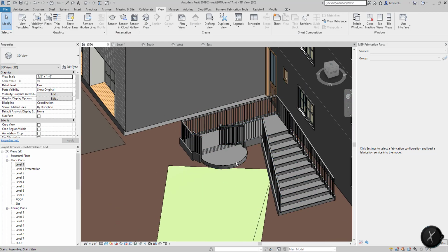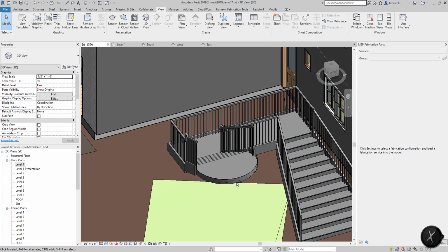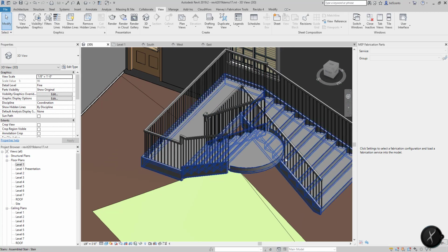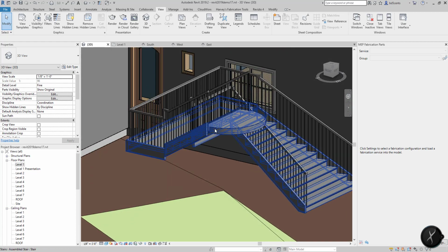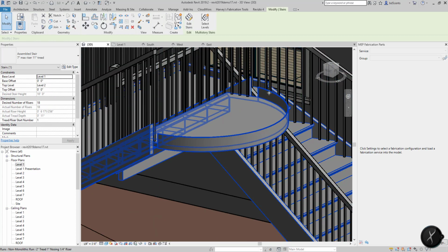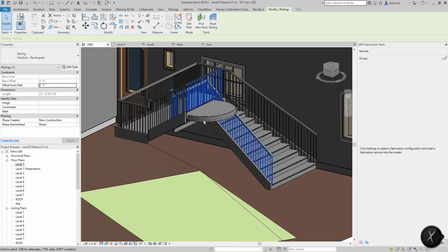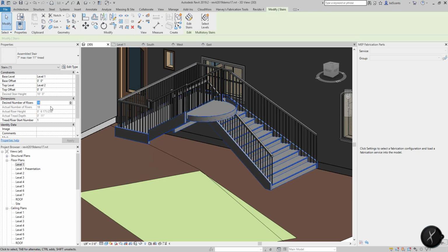And so I made some typical normal user mistakes that each one of you will probably make throughout the creation of stairs. And you'll notice that my riser's been created and I have that sort of platform up there. I also have this sort of boundary line. Now, I may not want that, but in this particular case, that's the tread that's showing up. So we can actually remove a riser, and let's just see what happens here.